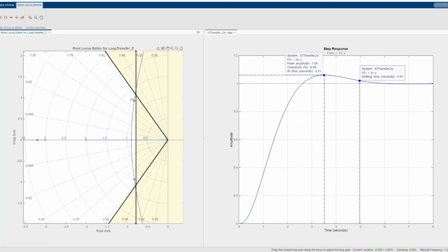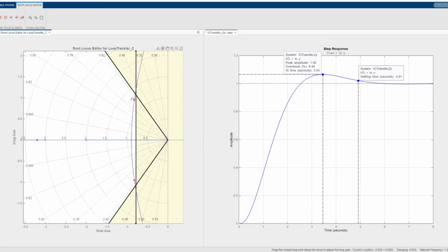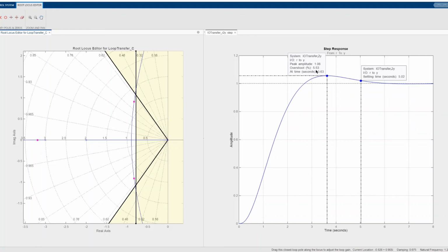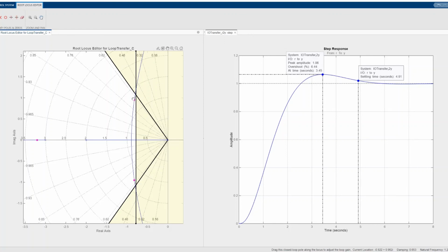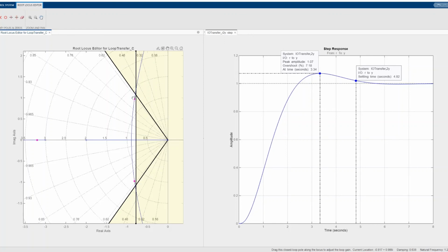It is now approximately 6%, about 5.5, but the settling time is now a little bit larger than 5 seconds. So if I win something here, I will lose something there. There's really an optimum. I can of course go back, and that will make my settling time better, but the overshoot will increase, though still within the specification, so there is no problem.